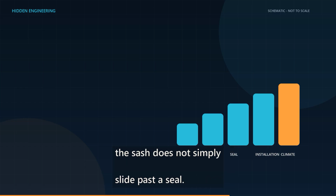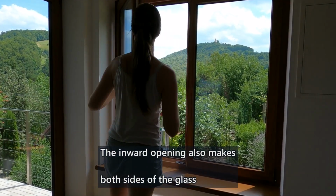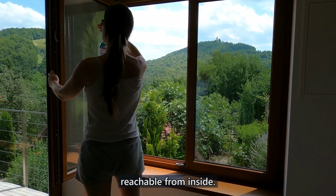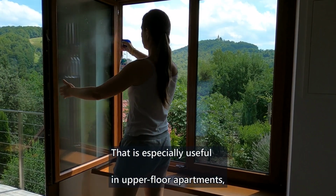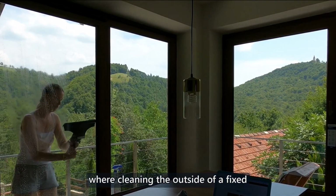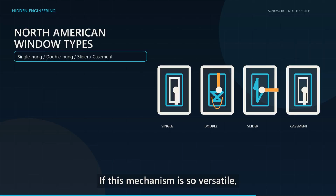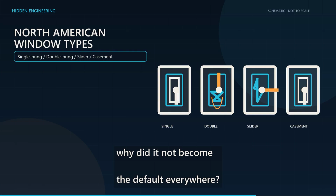The sash does not simply slide past a seal. The hardware pulls it into the seal. The inward opening also makes both sides of the glass reachable from inside. That is especially useful in upper floor apartments, where cleaning the outside of a fixed or outward opening window can be difficult. If this mechanism is so versatile, why did it not become the default everywhere?